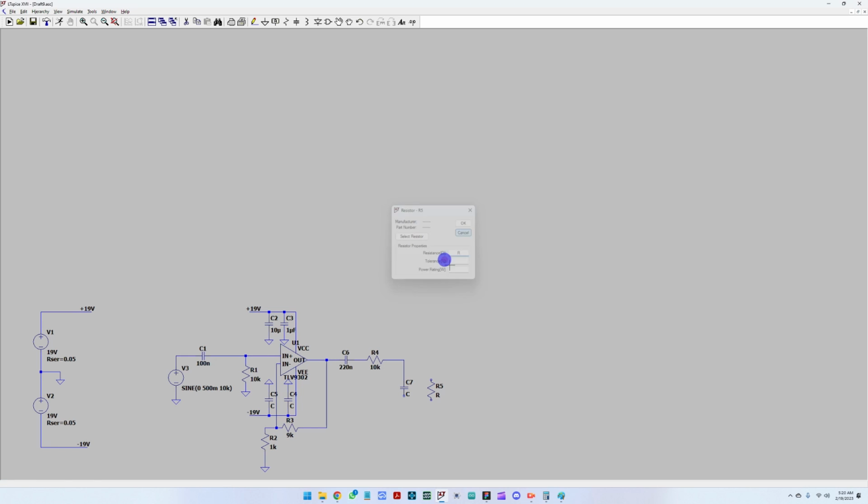And for the low pass filter, let's take maybe a 330 picofarad capacitor and a 100 kilo ohm resistor. So with this R5, you can also control the volume here. If you replace this with a potentiometer, this could be an option.